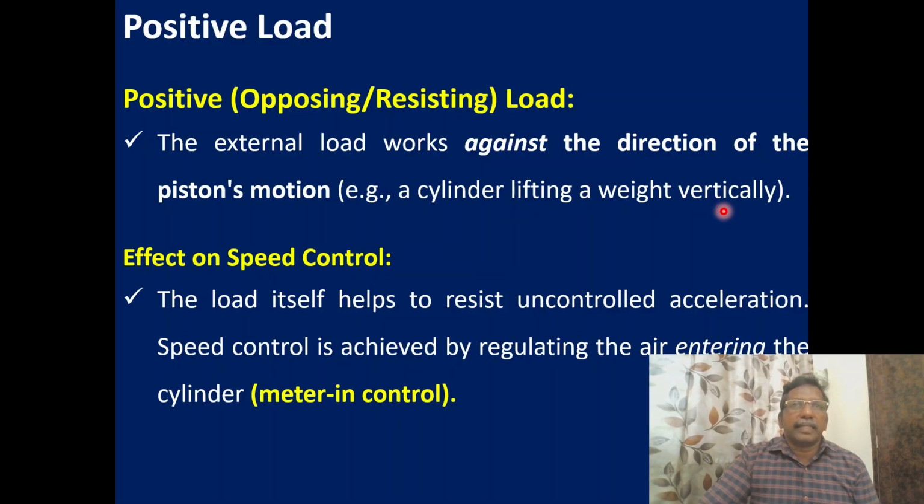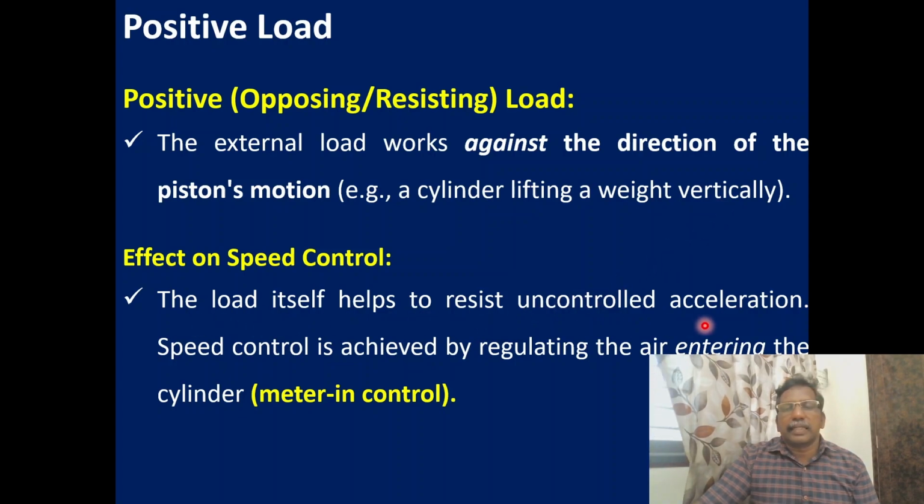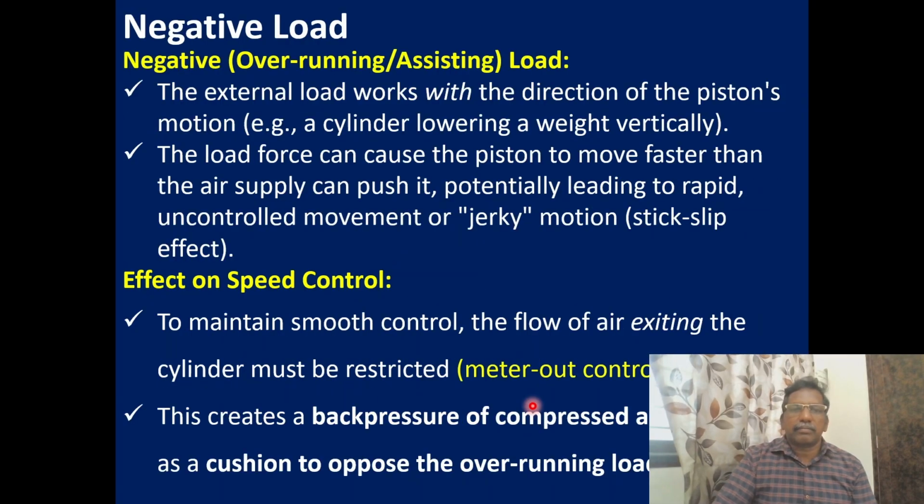For that purpose, we can use the metering-in circuit. The load itself helps to resist uncontrolled acceleration. Speed control is achieved by regulating the air entering the cylinder. So metering-in control is used.